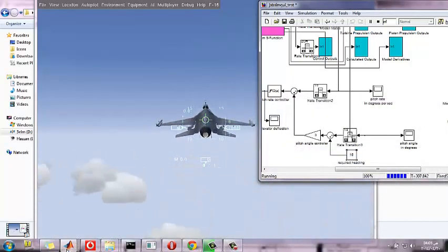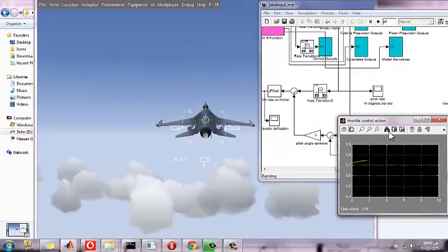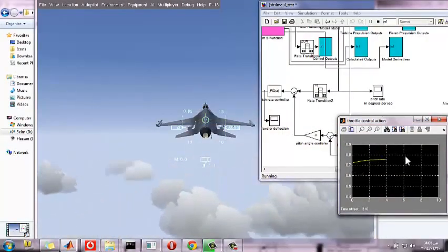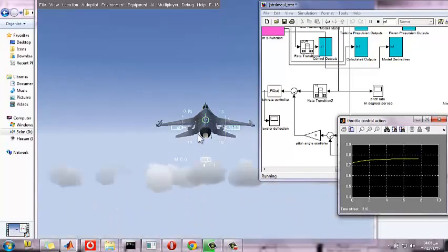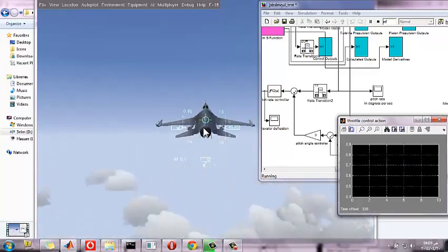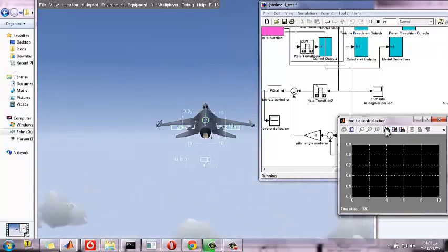Okay, it's just changing its attitude, and then we see the throttle, it's increasing, and this is logical because right now the aircraft has a component of its weight trying to resist its motion, trying to make it slower, and then the throttle has to be increased so the aircraft can maintain the 300 knots that we ordered. Okay, you can notice that it oscillates.